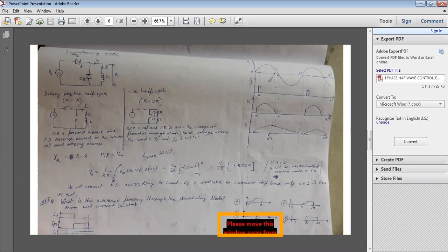You can see in this waveform picture that the voltage, this is actually the thyristor voltage, starts at alpha and ends at pi. After that, no conduction, output voltage is not available. From pi to 2 pi plus alpha we will not get any voltage output, but current is flowing from alpha to pi, and then again pi to 2 pi plus alpha.